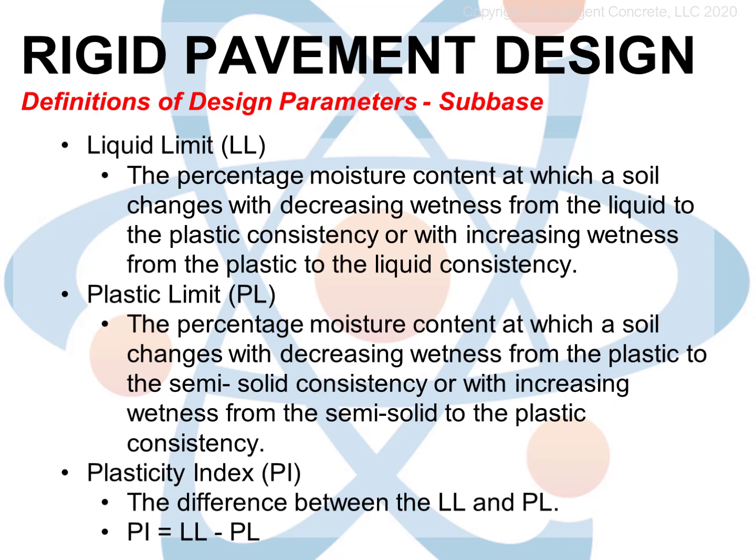Some critical characteristics of the soil which must be considered are known collectively as Atterberg limits, which are called the liquid limit, the plastic limit, and the plasticity index. Whenever a soil is known to have a significant percentage of silts and clays, more than 20 to 30% depending on the proposed construction, these tests should be run, regardless of the source of the soil composition data. They can be performed rigorously in a lab using specialized testing equipment or can be estimated in the field using only one's hands and an accurate scale.